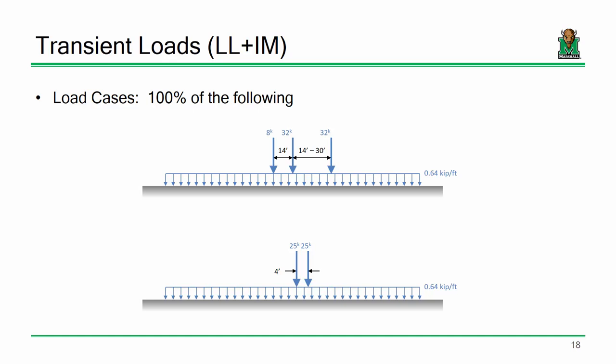We're going to cover it in detail. Okay, now that's the simple part. The axle spacing. If you're the engineer in charge of this project, would you put that axle spacing at 14 feet or 30 feet? 14. You want to lump those loads as close to the center as you can, right? Make sense? Okay, so yeah, it's variable spacing, but sometimes there's a little bit of logic that comes to that.